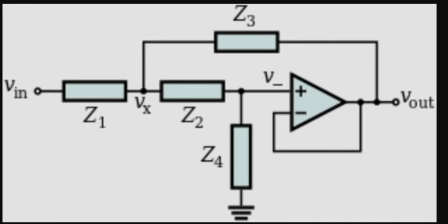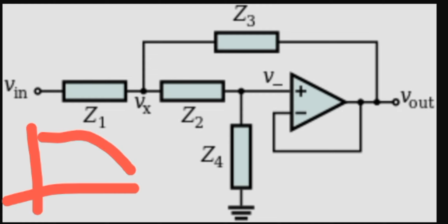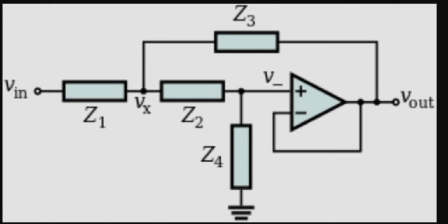So that's the typical behavior of a low pass filter, where the characteristics will look like this. You see that somewhere here you have FC in the middle, and here at this node you have the filter cutoff frequency, and this is your pass band, this is your stop band. So with that said, we have this filter response.